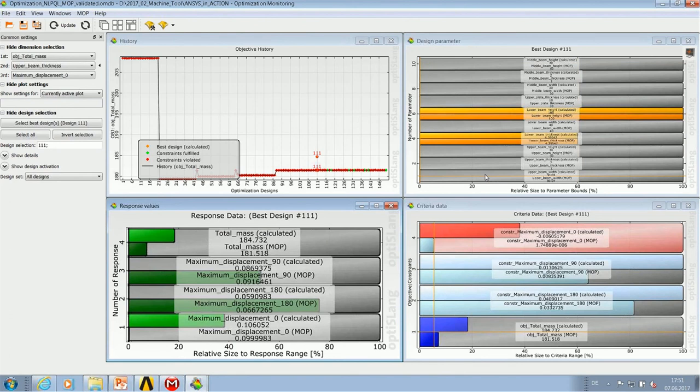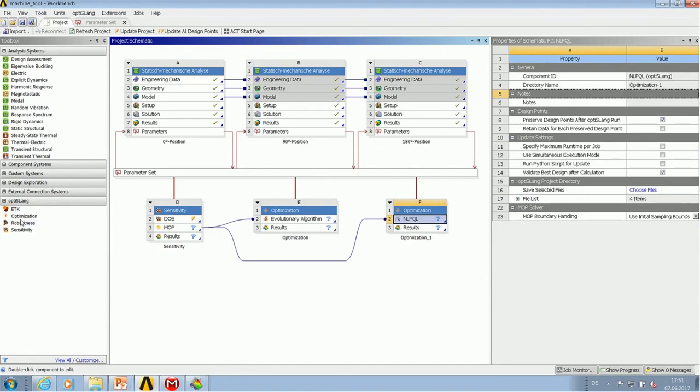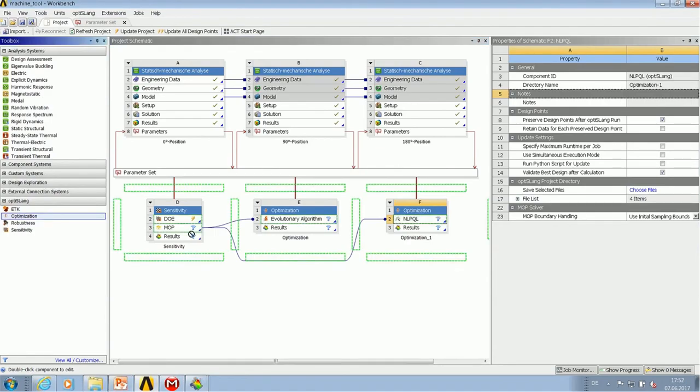We could redo a single objective optimization on the MOP by changing the constraint a bit, reducing the possible deformations. Or, if we are not satisfied with that, we can now do an optimization with a direct solver call. We may do the same, but not on the MOP.